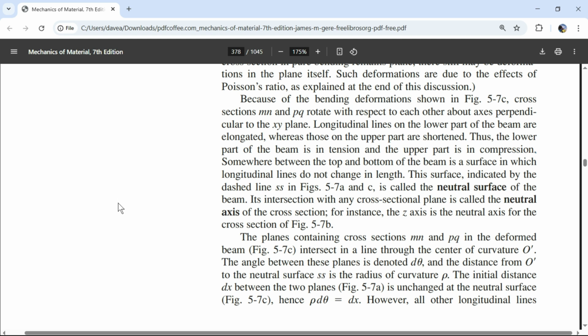Cool, and you say this much change in length happened at 100 pounds. Let's double it, and then you realize, oh, I have twice as much change in length. Then you go to 400 pounds, and I got twice as much. Then you go to 800, got twice as much as that. And then you just have this linear relationship up until where bizarre things happen. With steel, it just turns into Play-Doh.